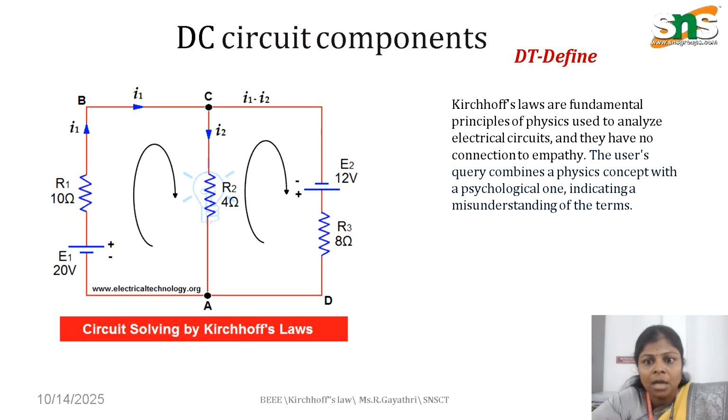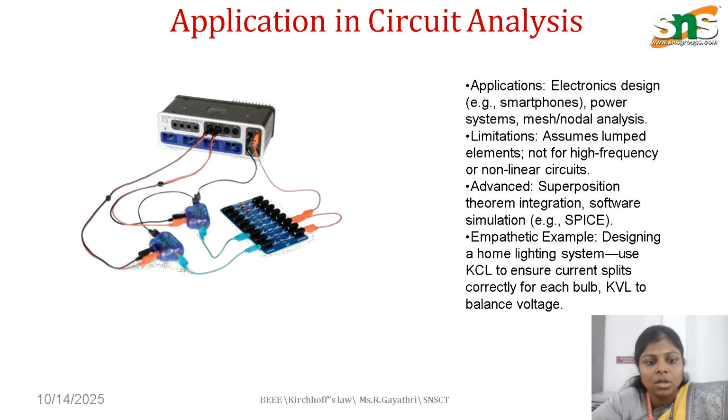Then coming to the definition part, Kirchhoff's laws are the fundamental principles used in complex circuits as well as simple circuits to find the current flowing through a resistor as well as the voltage drop across the resistor. The applications in circuit analysis are in power systems, mesh and nodal analysis, and also to find resistors in parallel, where the KVL and KCL laws can be used. But the limitation of these laws is that they cannot be used for high frequency or non-linear circuits.